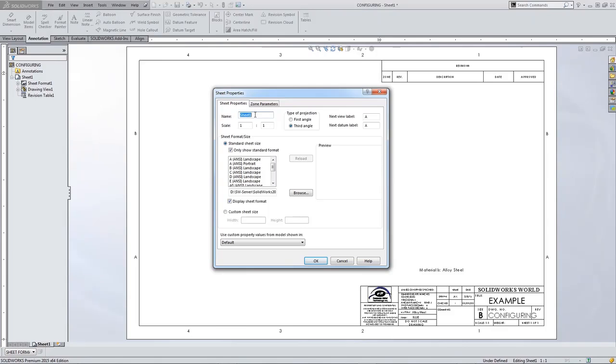It remembers the letters. So if you left off on G, and then one of your counterparts tests it, he's like, why every time I start a drawing view does it start with I for a detail? Can't we start at A? It's because it saved that information, so you might have to zero this back out to A. So don't worry, it'll probably happen.